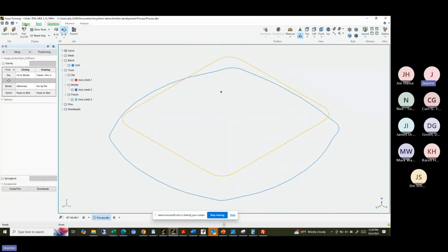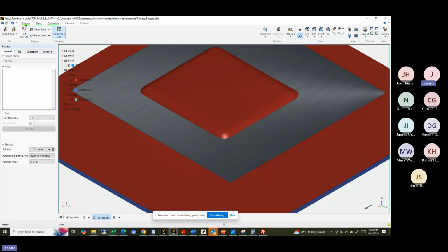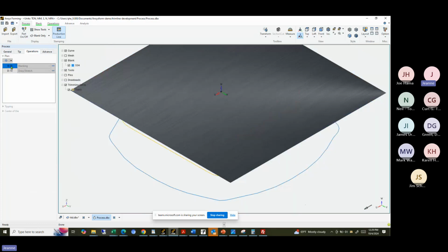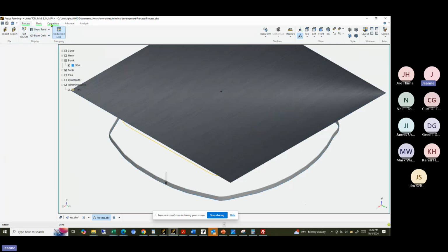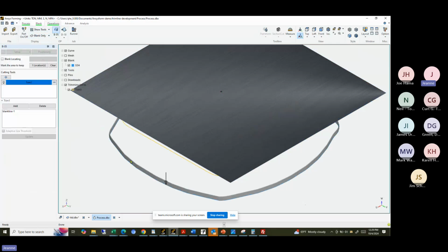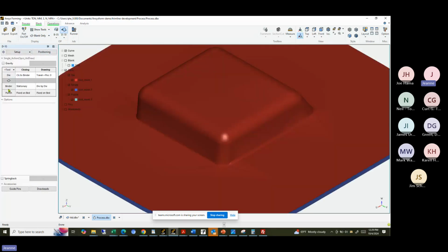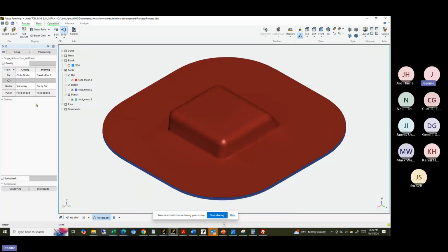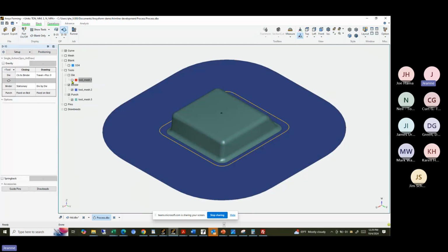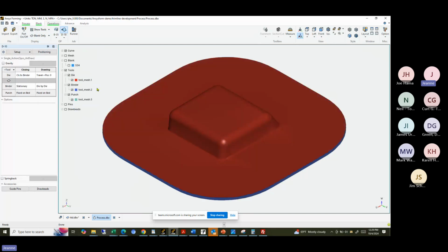So when you go to setup in the process operation, you have the draw. You need to add a station called blanking. Blanking is actually just a trim operation, which is the initial guessed trim shape. Then set up the draw: one die above, this is single action, and the punch on the bottom. You will see the binder and punch all start from home position.